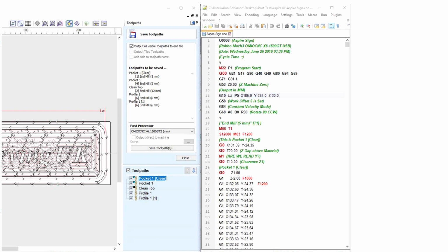The coordinates of the origin of the coordinate system specified by the P number are reset to the coordinate values given, in terms of the absolute coordinate system. Only those coordinates for which an axis word is included on the line will be reset.